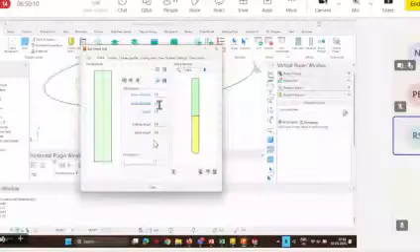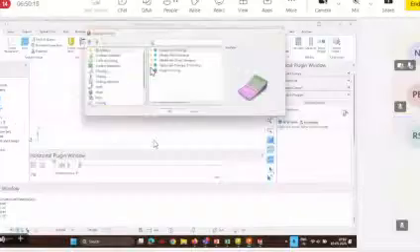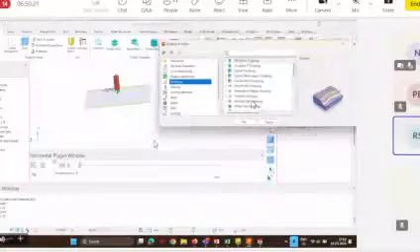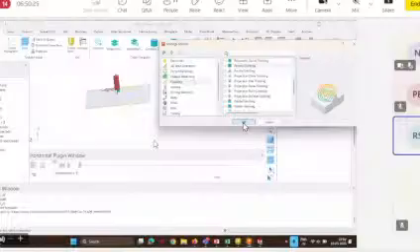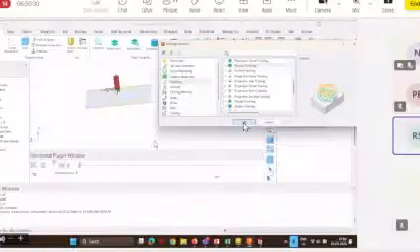Go to create toolpath, then go to finishing. In finishing, if you go to one strategy called pattern finishing, select it and click OK. Now in the pattern you can select one curve, and we'll just select one by one. Work plane. Then you can click the block. The tool is already created. Limit is not required currently. Then pattern is there. Then tool axis, instead of having vertical, we can put from line, from curve.